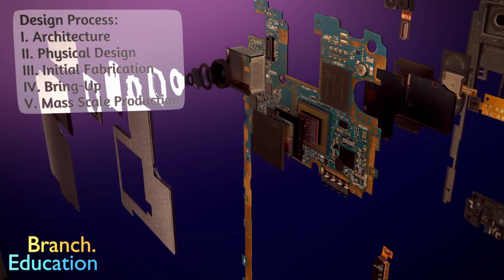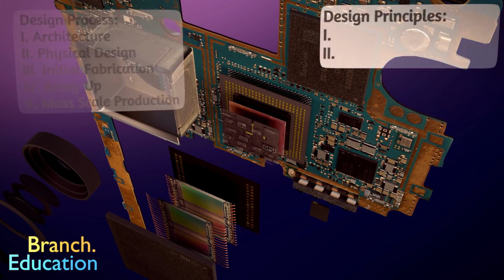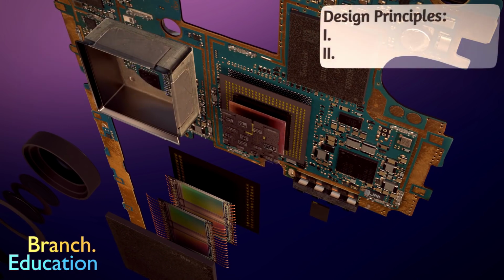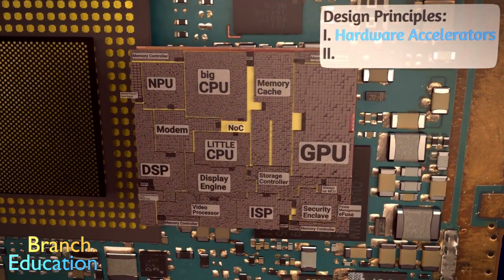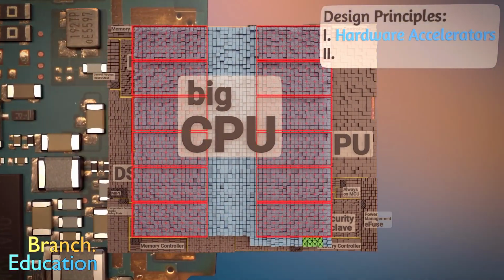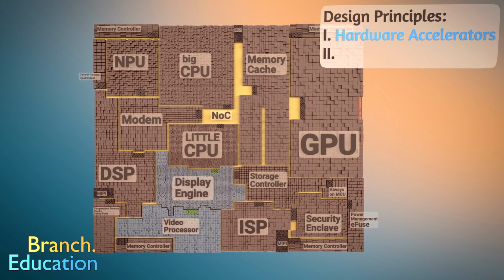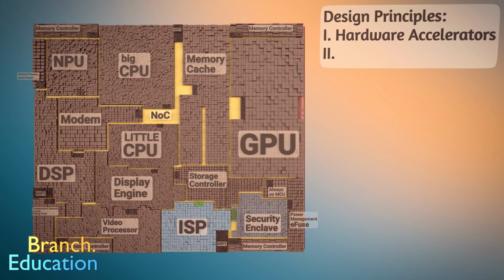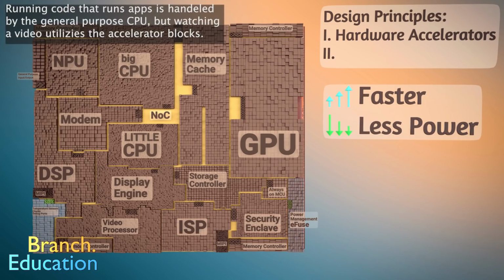Instead of talking about the entire design process, which you can find in the creator's comments, we're going to discuss two design principles of the SoC. The first principle is called hardware acceleration, and this principle deals with the fact that instead of having a single, very powerful general-purpose CPU with a lot of cores, this chip has a variety of special-purpose blocks dedicated to performing specific functions. These special function blocks, or hardware accelerators, compute their tasks faster while using significantly less power than if the same operation were performed by the general-purpose CPU.